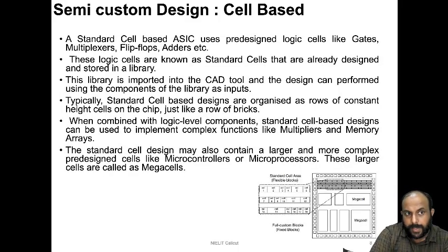Now if you look at the next type of semiconductor custom design, that's called cell-based design. You can see the picture on the bottom side of the slide. You can see that in the case of cell-based, some standard cell area is there, as well as full custom block area. Okay, so standard cell-based ASICs also use predefined logic cells like gates, multiplexers, flip-flops, adders, etc. These logic cells which are predefined or pre-designed are called standard cells.